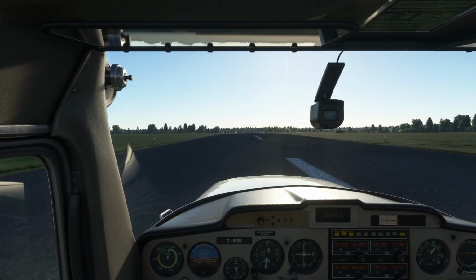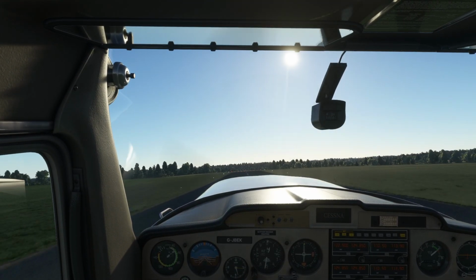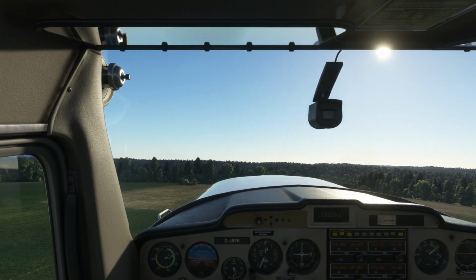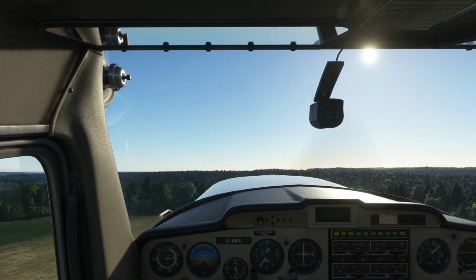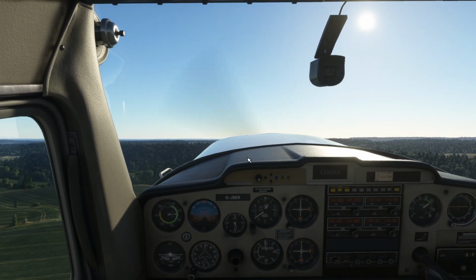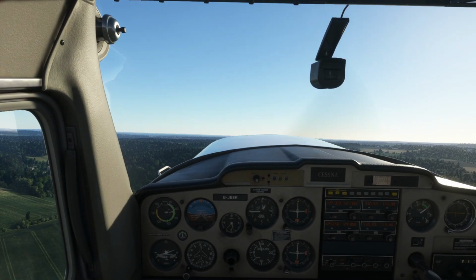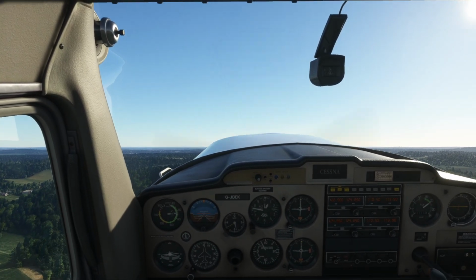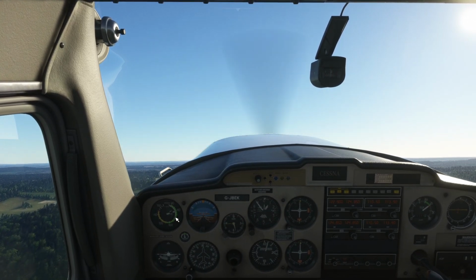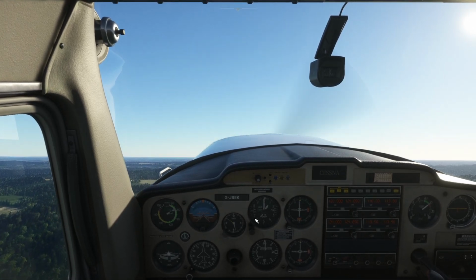So full throttle, flaps up. Don't need flaps for takeoff on this runway, so we're going through 50 knots, rotate. Back to 10 degrees offset on the nose. And then turn another 10 degrees, so we're going out to 220 degrees for our climb out away from Booker, and we keep the nose up, so we manage the speed with altitude now to get out to our 1,500 feet altitude, which is 1,000 feet over the airfield elevation.